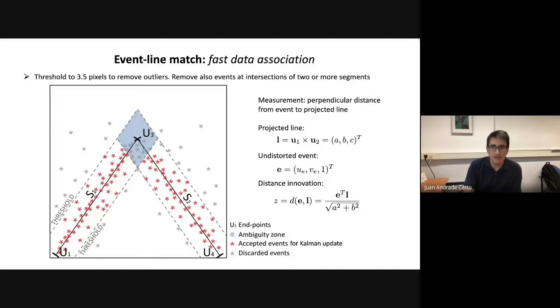With that, we are able to estimate a linear speed of approximately 0.7 meters per second and an angular speed of 0.8 radians per second. And our ground truth is being matched against an OptiTrack system that we have in our laboratory. And as you can see, the root mean square error is below 1 centimeter for X and Z, and a little bit above 1 centimeter for the Y direction.